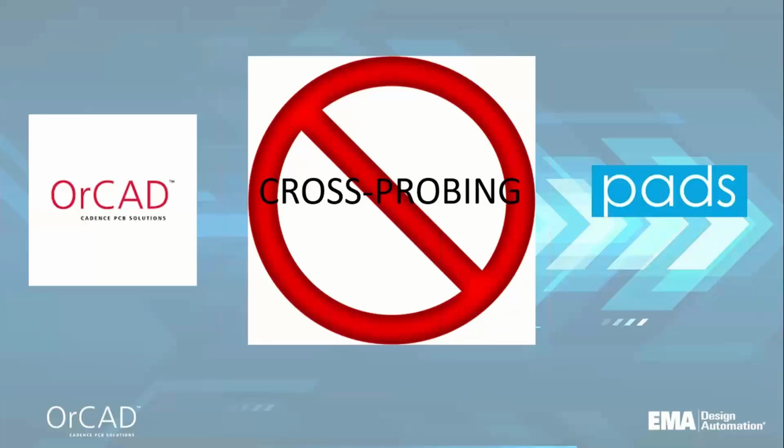Cross-probing. One thing is you cannot cross-probe between OrCAD and PADS. There are a lot of engineers or companies that design in OrCAD, but then they lay their boards out in PADS. One thing that I always try to sell service bureaus is to take your OrCAD into PADS Logic and then you can do PADS, but the problem with service bureaus is every time they get a new schematic, they have to do a translation. So it's kind of a monotonous thing to cross-probe with OrCAD and PADS.